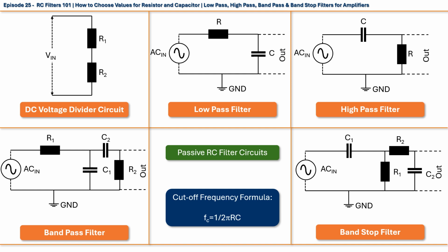By definition, resistor and capacitor in series makes RC circuit. It is almost identical to voltage divider circuit, where instead of two resistors in series, now we have a capacitor and a resistor. Depending which component is connected to the ground, we have low and high pass filters. For low pass filters the capacitor is connected to the ground, and for high pass filters, the resistor is connected to the ground. The word pass in this context refers to all the frequencies that pass unattenuated through the RC filter. Unattenuated means that they will pass through the filter without reduction in amplitude.